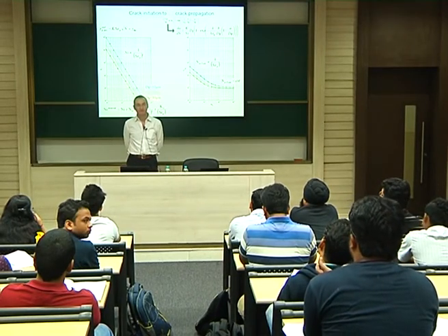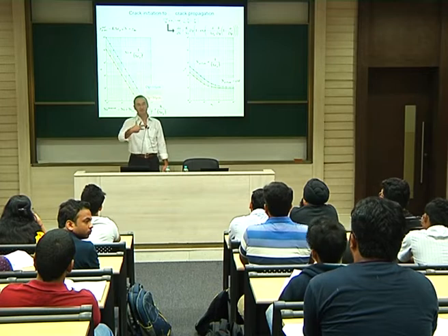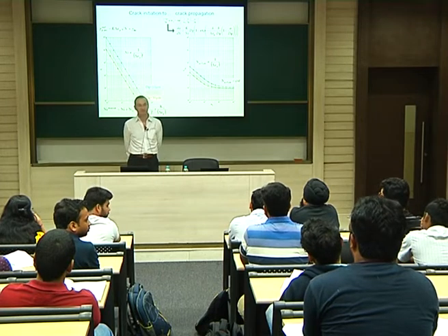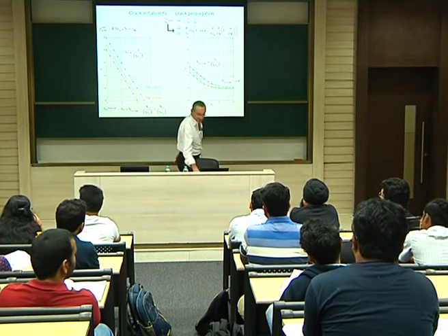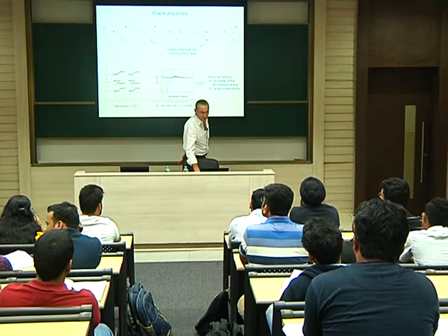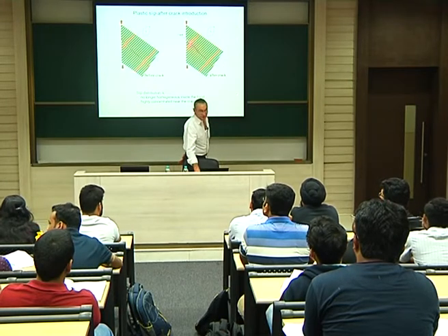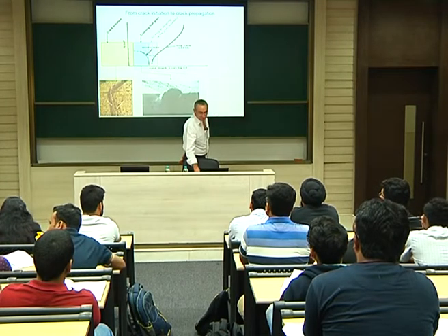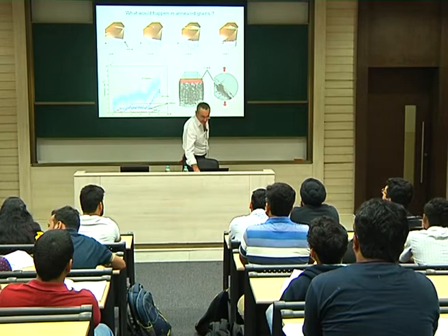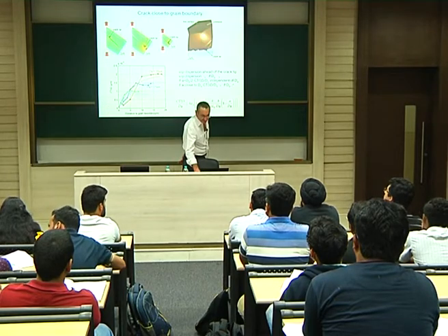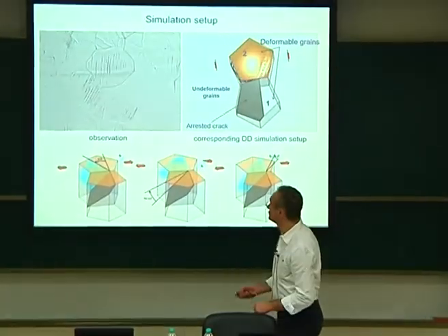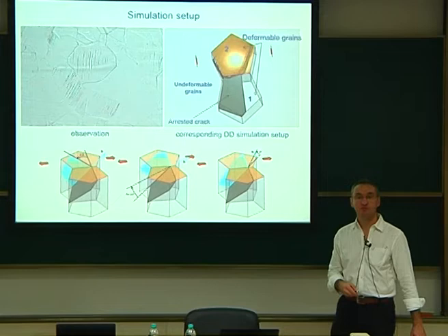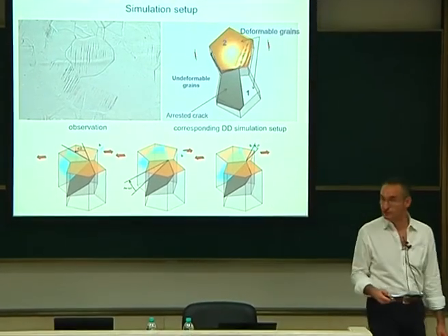Yes, sure. With the tilt angles and so on, this is the misorientation there, yes. The disorientation between the two grains gives you the orientations of the slip systems, compared from one grain to the next. Here we just define the two orientations by those three parameters. You see, those three angles.